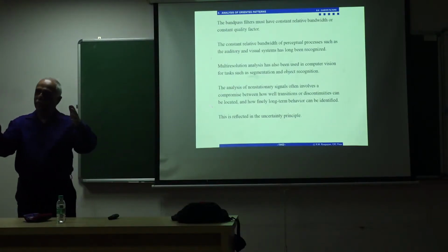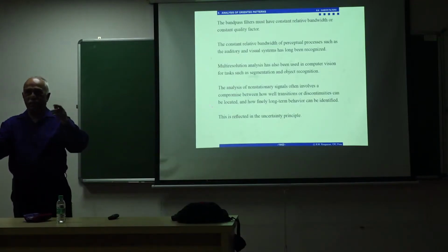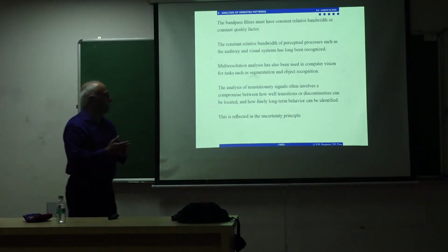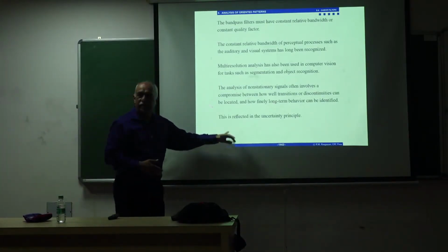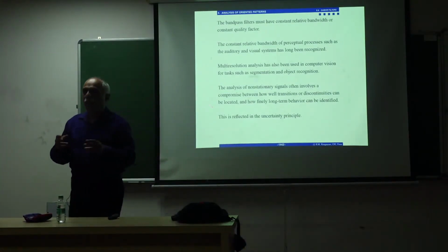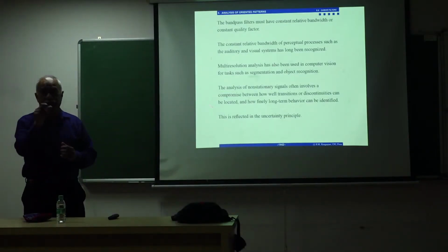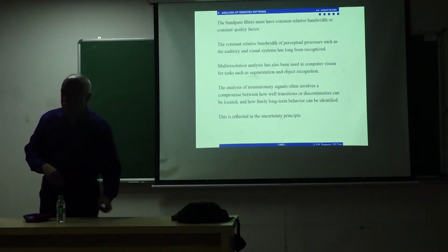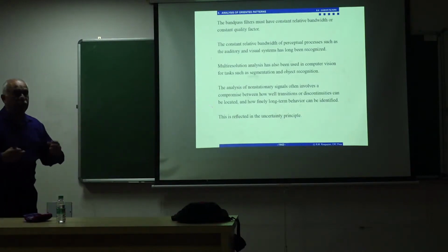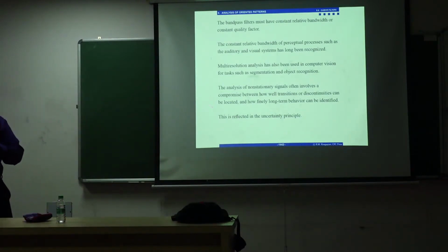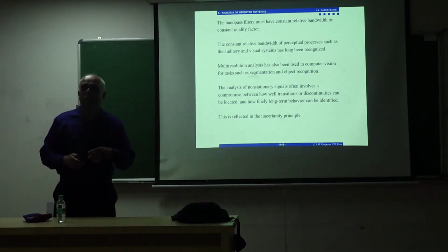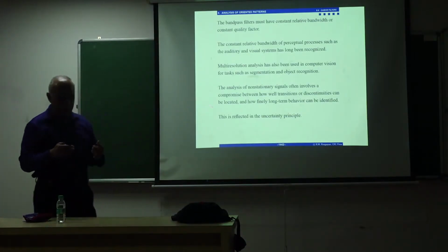You're not looking at the entire voiced signal. So there are these conflicting or contradictory requirements, and that is related to the uncertainty principle. So you use multi-resolution. You use wavelets of multiple durations, scale factor, and then try to put all the information together and analyze the image with information related to fine detail and coarse detail.